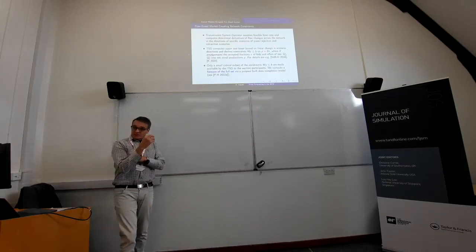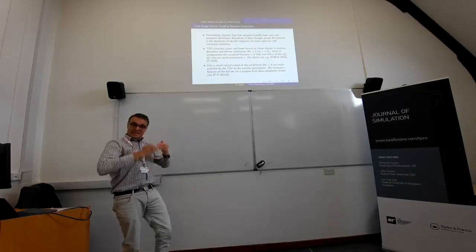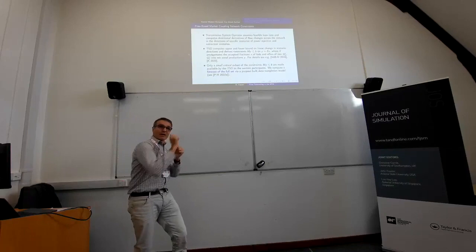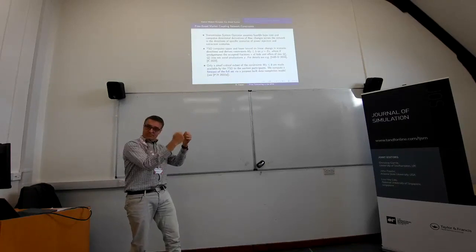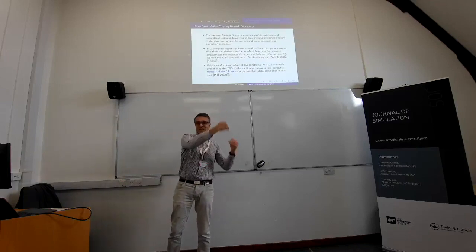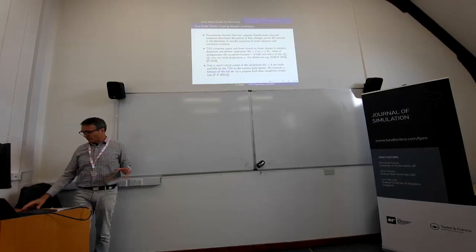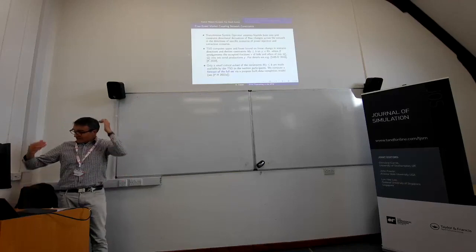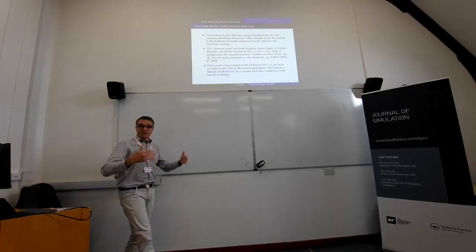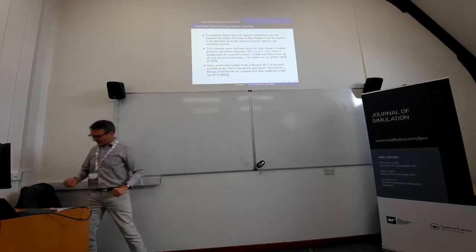you have one line and you take a directional derivative in the direction of that scenario. And then the question is, how much can you scale up this scenario, the base scenario plus a multiplier times that vector, before you start exceeding the allowed power load on one of the lines? And then they produce maybe multiple constraints.